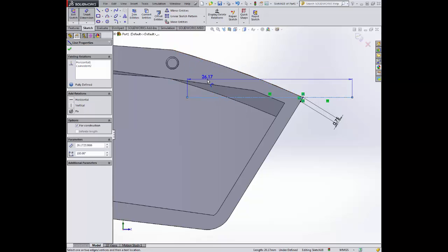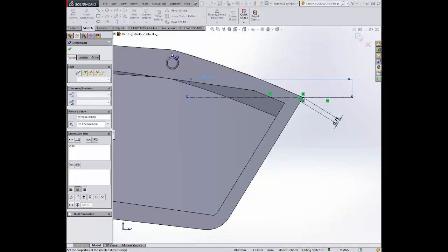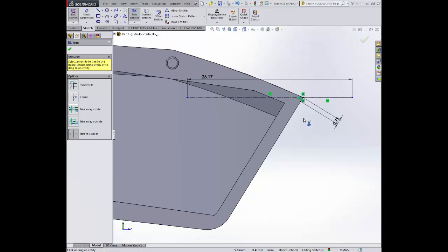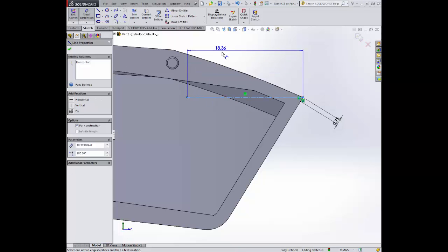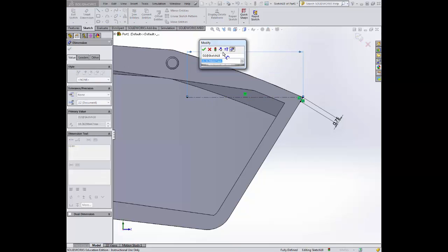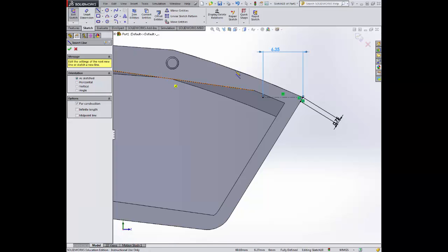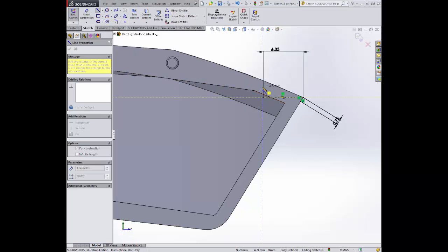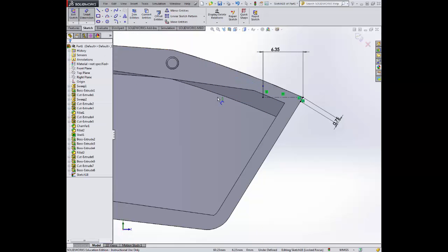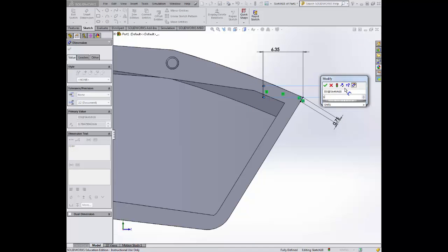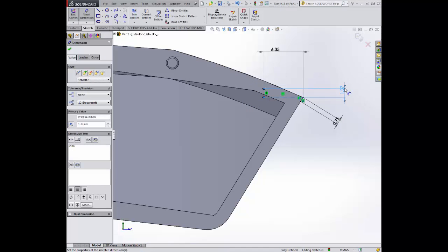However, my line is now too long. So red cross that, and then we need to do a bit of trimming. Trimming out the original bit of line, the added bits of line we don't need, say yes. Redimension it. .35. Coming up. Smart to mention that one too. 1.37, so a very precise measurement in there too.